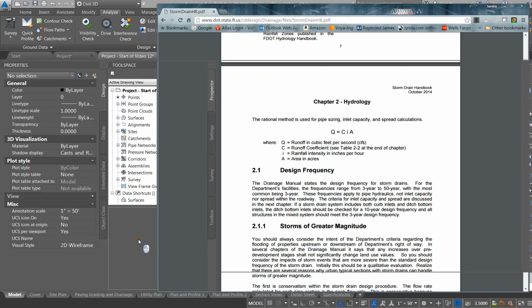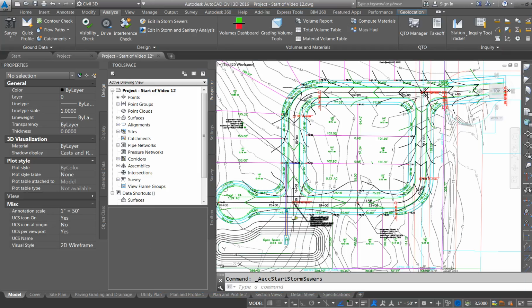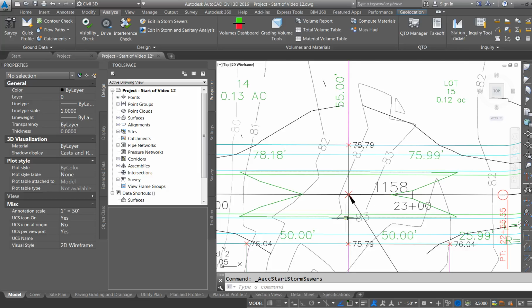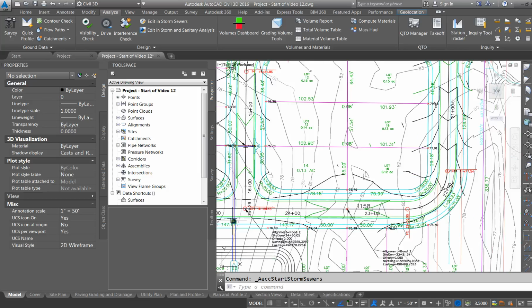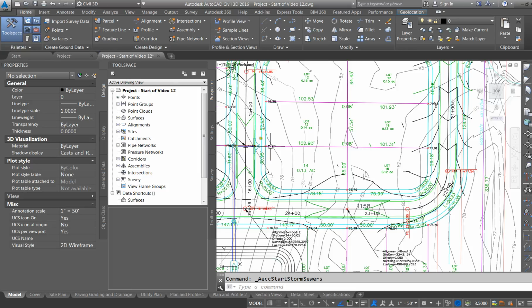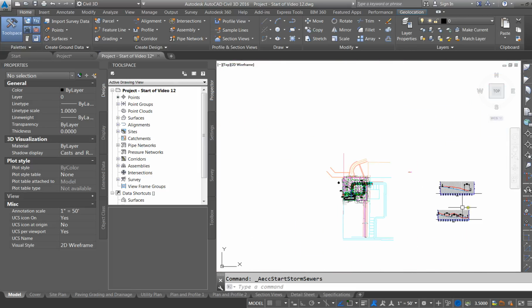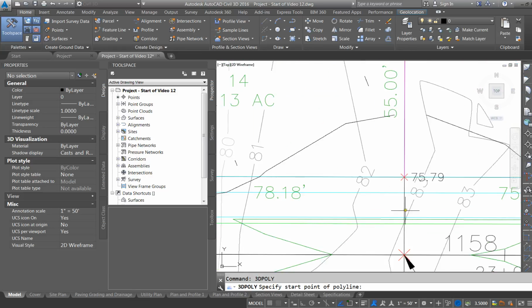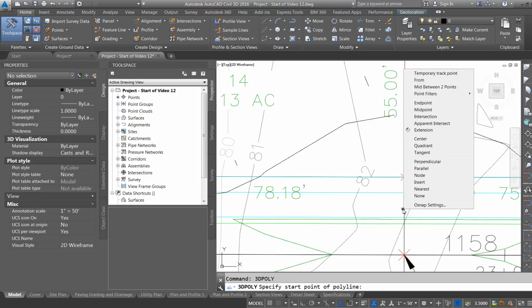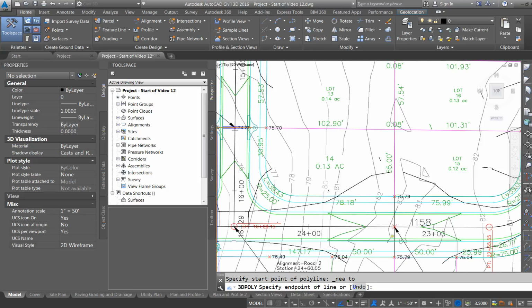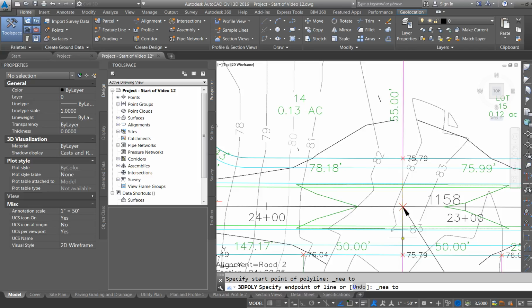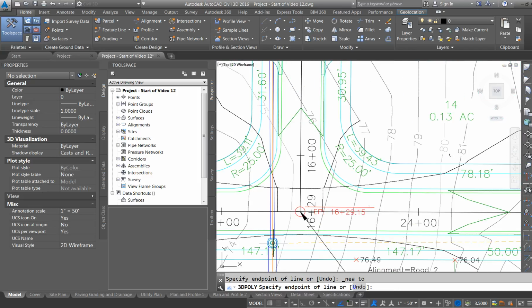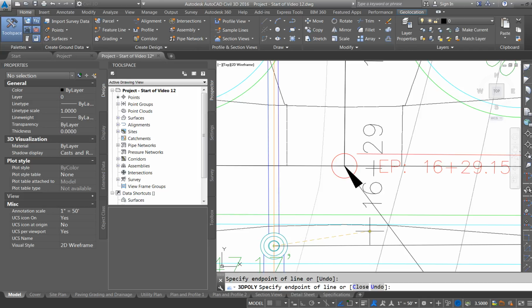All right. So we've got one line done. Now we're going to go ahead and have a second inlet set, and we're going to connect to this group. So all of these pipes need to be designed and need to be imported into our structure. So I'm going to go ahead and create another 3D polyline, and I'm going to start here on this low point. And I'm drawing it as I would drain to it. And it's going to connect to that center point.